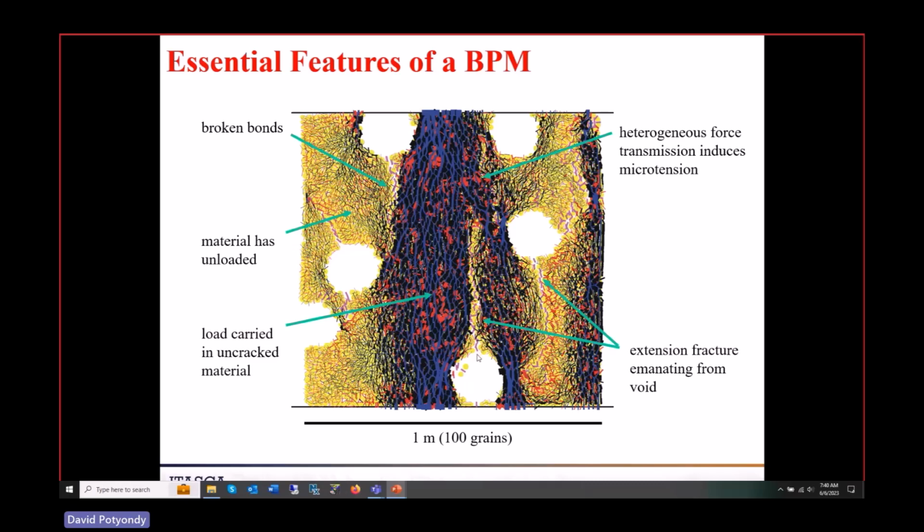Here's another crack. These extension fractures in this system, we have these stress concentrators because of these holes. And above and below the holes, if we're squeezing vertically, we're getting sites of tension. And those sites of tension are higher than the tensions inside of here.